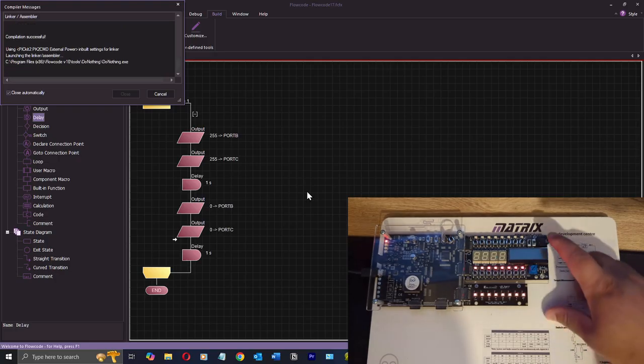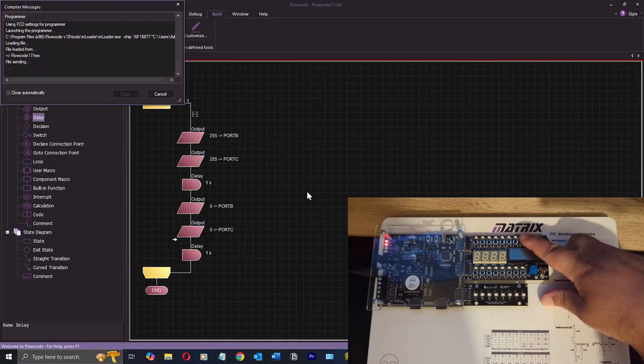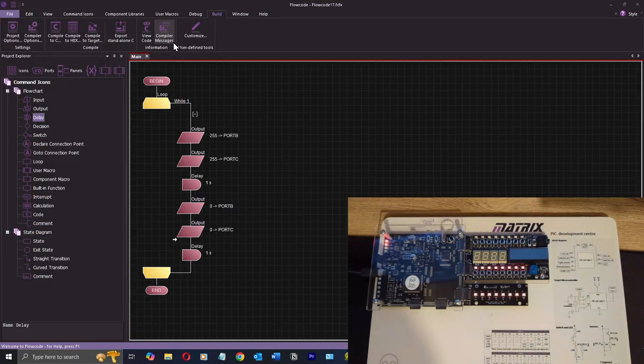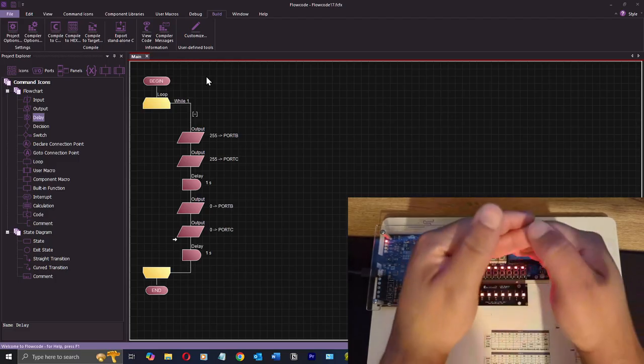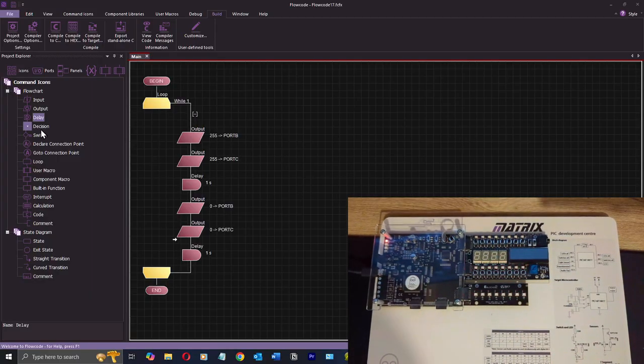So next up would be when I press bit 0 here, to then change the delay. I think you press bit 0, change the delay to make it blink. Was it fast or slow? I don't know. And then when you press the other button, change the delay. So we'll use a delay variable actually. So that's blinking now every 1 second on and off, as you can see. So we want it so that, let's read the input of our push buttons.